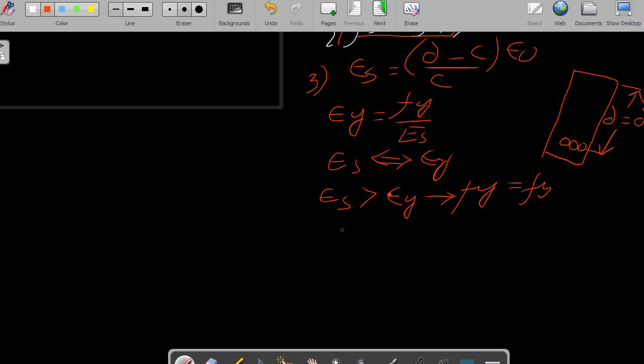So in this case the epsilon s value will be equal to epsilon t, if the steel is placed in one layer. If the steel is not placed in one layer, then epsilon s will not be equal to epsilon t, and we have to find out the value of dt. I already explained in part 6 or 7 how to calculate dt, and I will do some examples on how you can calculate the value of dt, right?